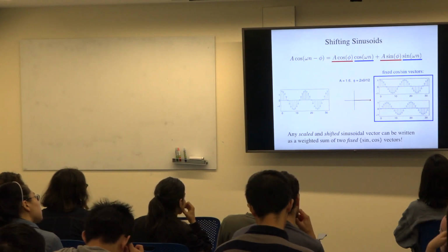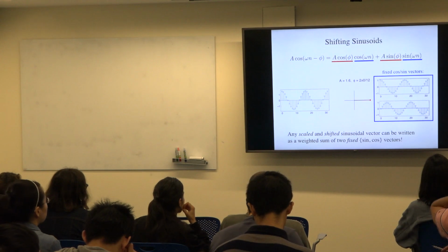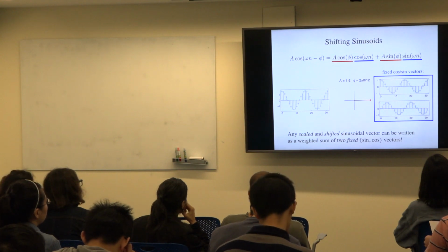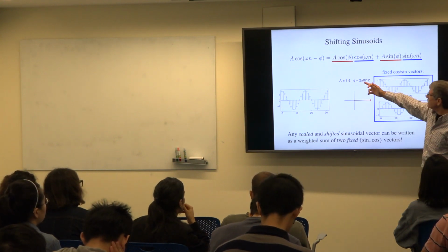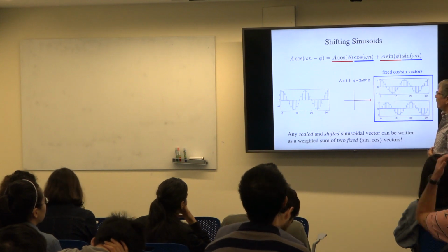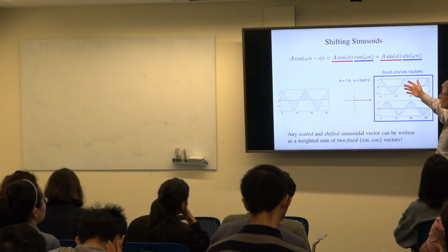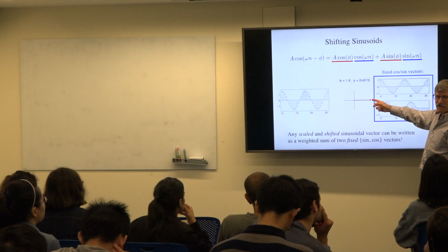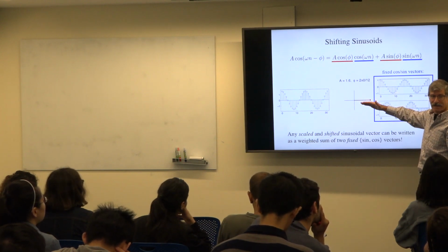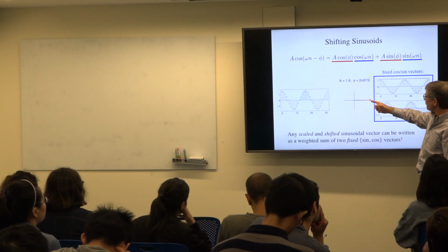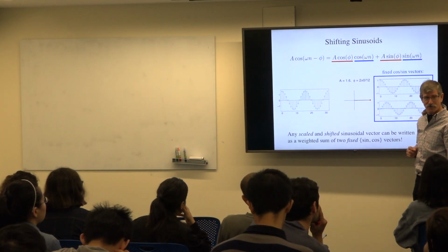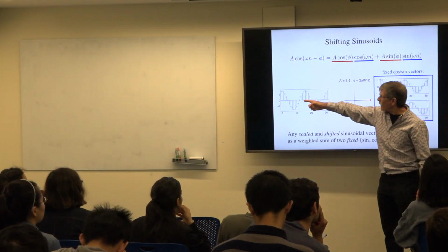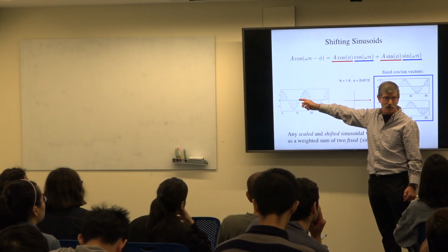What comes next? So as an example, a bunch of examples, I'll do this. Suppose the amplitude is 1.6 and phi is 2 pi times 0 over 12, say. Okay, so phi is 0, so we're not going to phase shift the cosine at all. So I've drawn a vector whose length is 1.6 and whose angle is 0, so it's on the x-axis. Now we're going to talk about the coordinates of that vector. X is 1.6 and y is 0 for this vector, which means we're going to take 1.6 of this and none of that. Add it together and get cosine with amplitude 1.6.